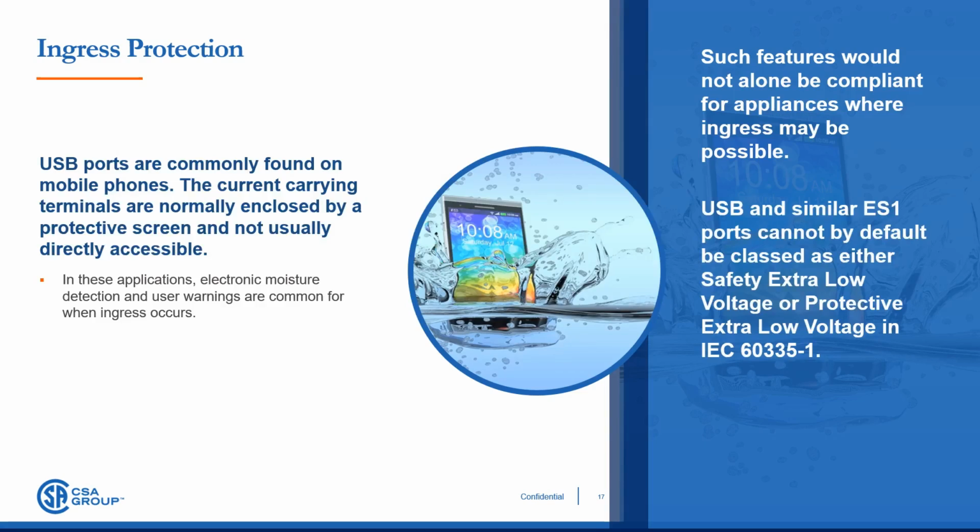Despite the IEC 62368 series permitting up to 60 volts DC for ES1 limits, the basic safety publication of IEC 61140 restricts this level to dry locations only, in subclause 5.2.6 in the 4th edition.